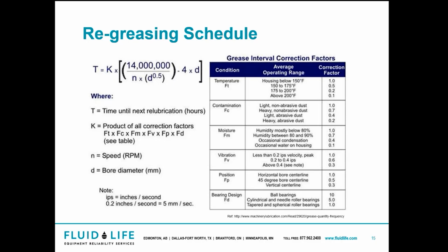And that is a service we do provide. We will come to your site and look at the bearings you have with some assistance from you. Like, hey, what are your electric motors? Then we pull up the frame size, pull the bearing from that, and give you a true re-greasing schedule and frequencies.